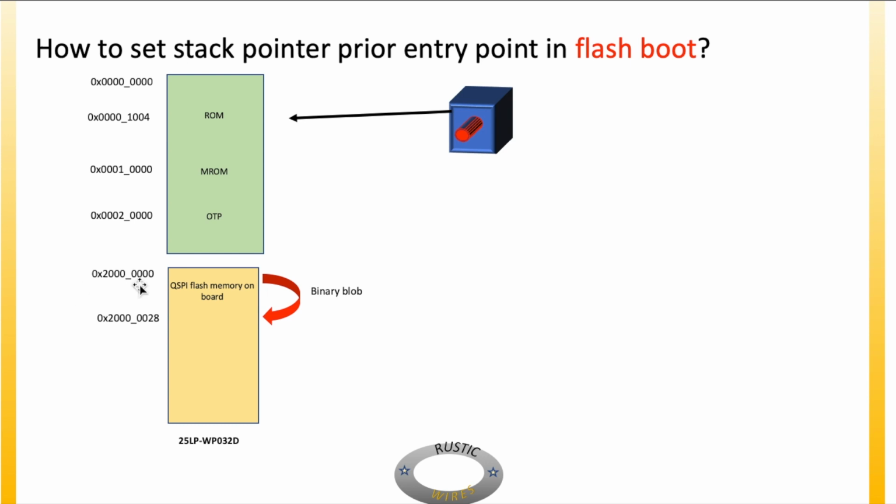So when you build and link Rust code, and if your _start is pinned to this location, then there's a very good chance that the stack pointer might not be initialized, or it might even have a stale value, or right after reset it points to an invalid memory.